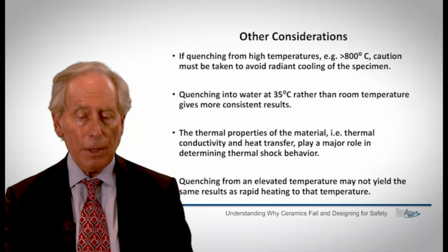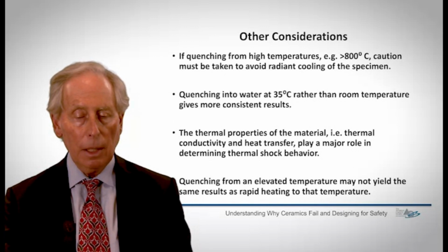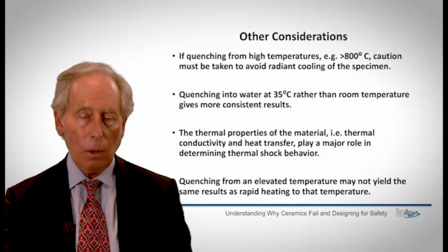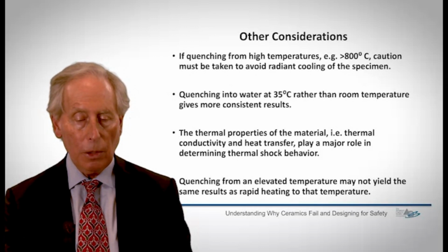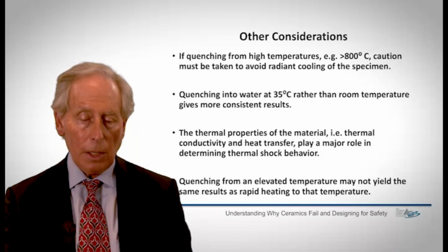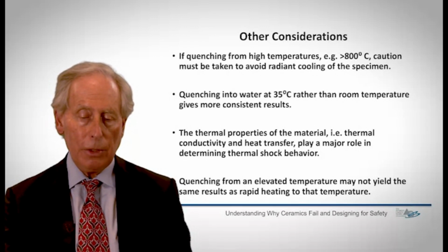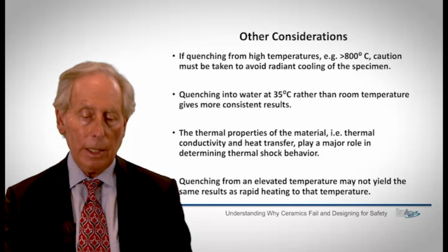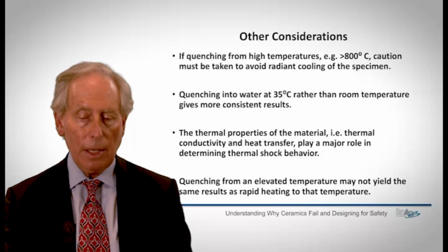And the thermal properties of the material play a major role in determining thermal shock behavior. So I think that's shown up in the equation, and that equation seems to hold for most materials. And also, I didn't talk about rapid heating, but quenching from elevated temperatures won't necessarily yield the same results as rapid heating to that temperature.